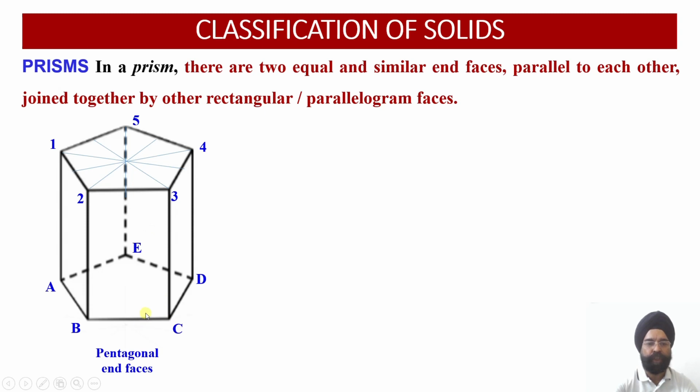Similarly at the bottom also, I am going to draw 5 projectors from the corners to the midpoint of the opposite edges over there. So wherever these 5 midpoint projectors join, they are going to give me the midpoint of the axis over there. So these are the axis location points. So from here you see the axis I have drawn. This point I have marked as O1 and this point I have marked as O.